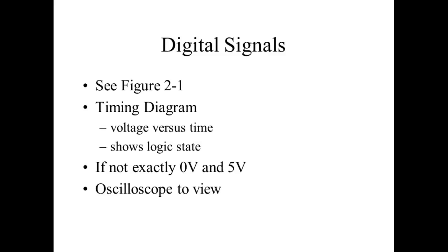So if you've got any spikes, if you look at a digital signal with a digital meter, you can't tell much unless it's moving extremely, extremely slow. So we start looking at some of these digital signals. What an oscilloscope does is allow us to look at voltage levels. All a scope will measure is voltage levels, but it looks at what's actually there relative to time.